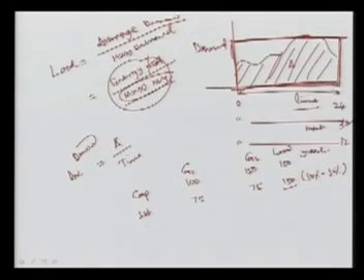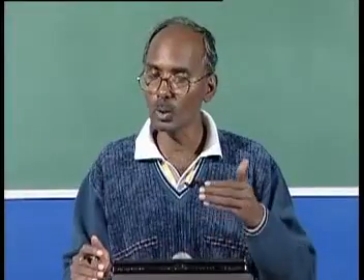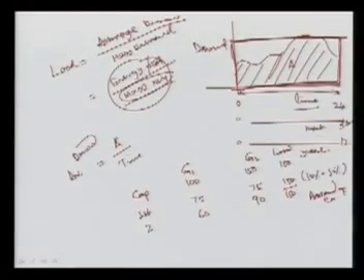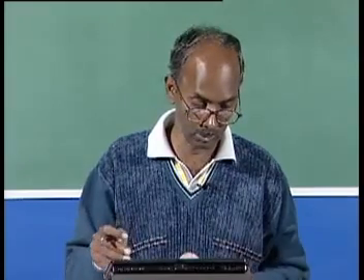Another criterion, second: we can load according to the capacity. This is 100, this is 150. So we load 60 here and 90 here, and again we just meet our load demand. It is loaded according to the capacity: where capacity is less, load less; where capacity is more, you can load more.